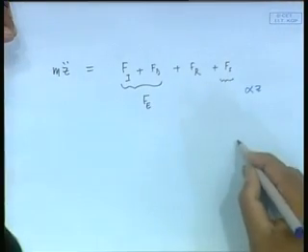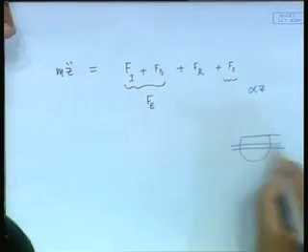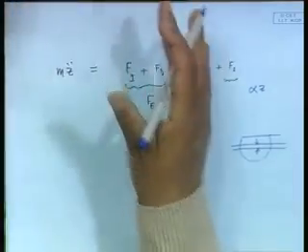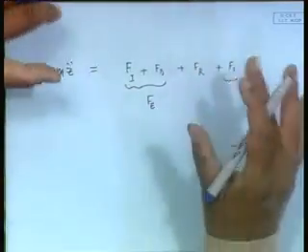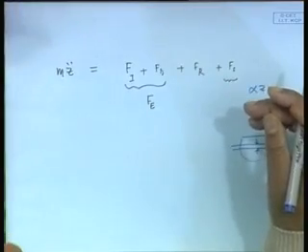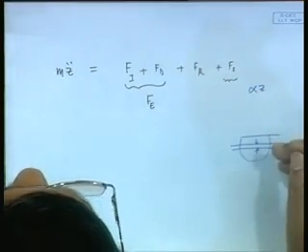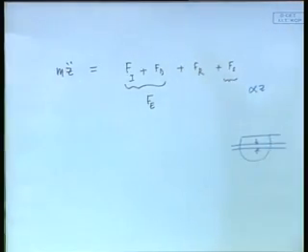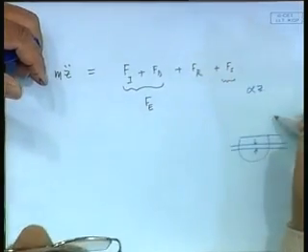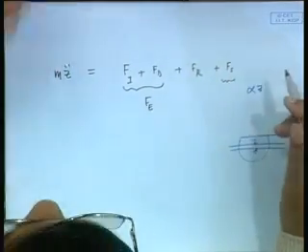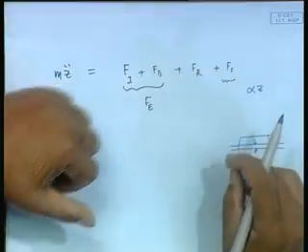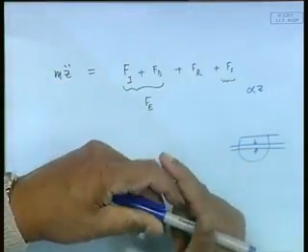If I have this body and I push it down by an amount Z, then obviously the force is rho g AW into Z. In other words, if I push down 1 meter, it is actually TPC, tons per centimeter, into Z, similar to that idea. So obviously this is linear with respect to displacement. Well, forget Z, let us take pitch or roll rather.